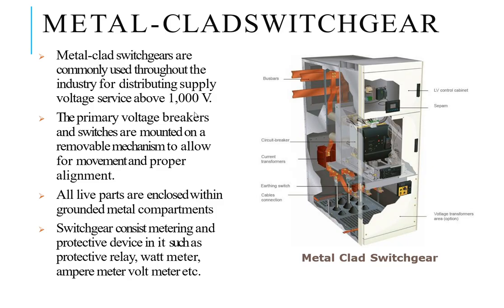Metal-clad switchgear is commonly used throughout the industry for distributing power and supply voltage service above 100 volts. The primary voltage breakers and switches are mounted on a removable mechanism to allow for movement and proper alignment. All live parts are enclosed within grounded metal compartments.